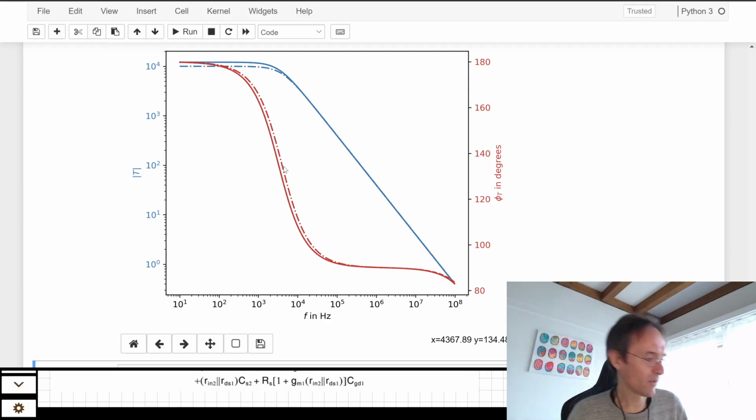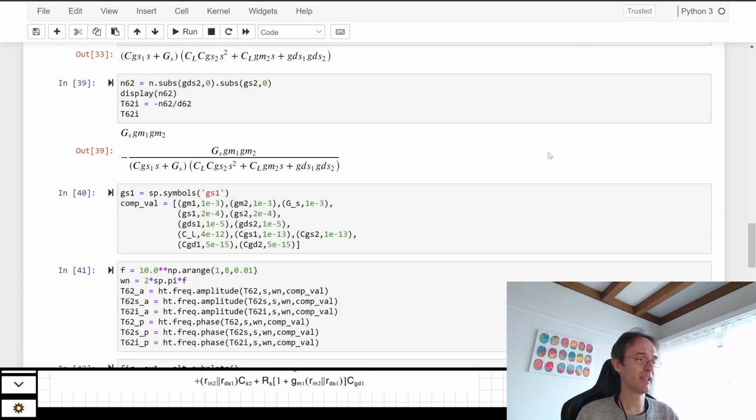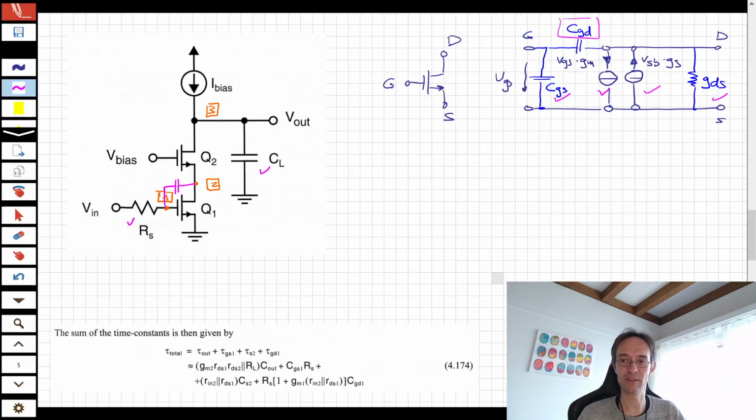So that was 50 minutes where I went from zero, empty sheet of paper, just a circuit on it, with all the explanations for students, to a simplified transfer function for that cascade gain stage, which has an advantage if you compare it to the original, that this one I think is much more correct, because the circuit here really doesn't have 4 time constants.